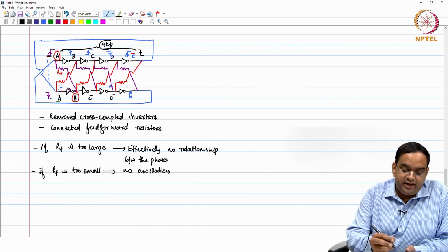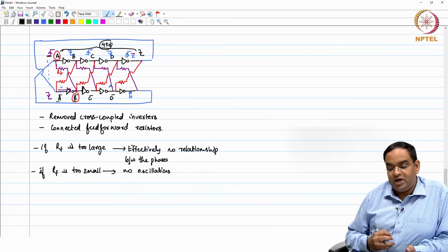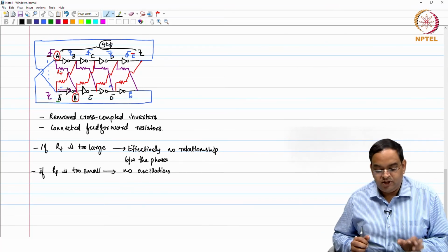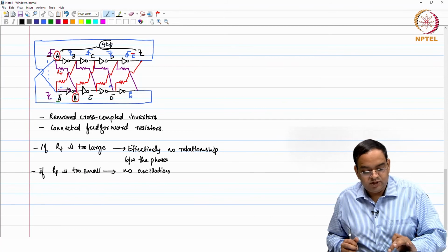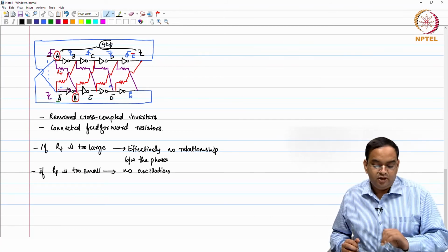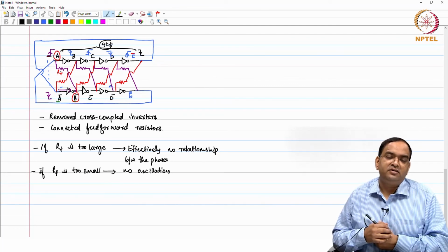An important thing here is that as soon as you use the resistor, you are loading your output nodes also, okay. So, if it increases the parasitic capacitors and other things, then the frequency will be lesser, okay. So, you have to try to minimize the parasitic capacitance which is coming whenever you add anything to this circuit.